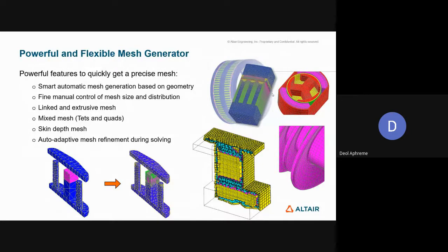Why I say it's appropriate to your project is, if you have too fine a mesh throughout the project, that will increase your solving time. It depends on how many nodes, and it also increases the computation power that you require. One CPU with 12 cores might not be sufficient to simulate such a project, or even if it is sufficient, it might take a lot of time to go through the linear solving process and the non-linear solving process and all of that. So there's a good trade-off that you have to make with meshing.